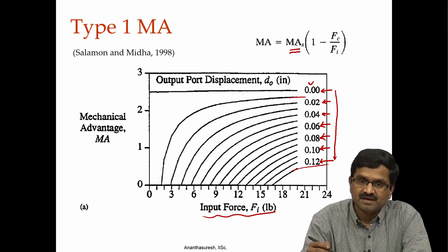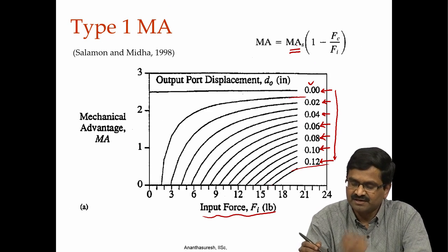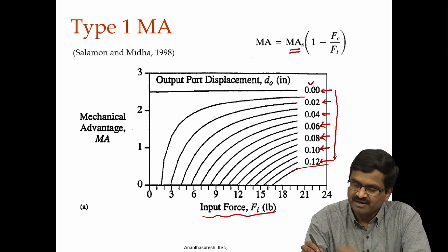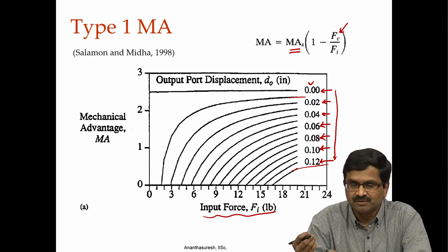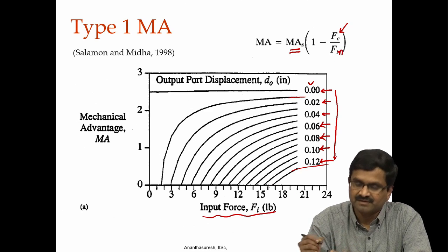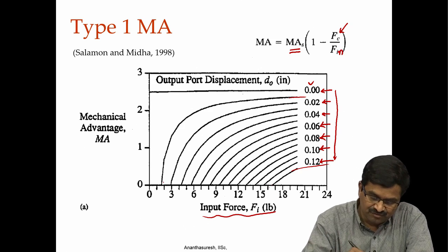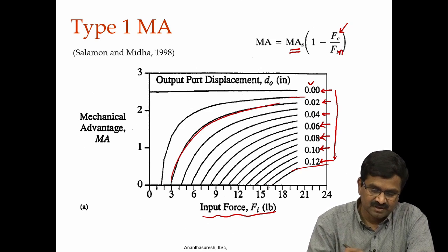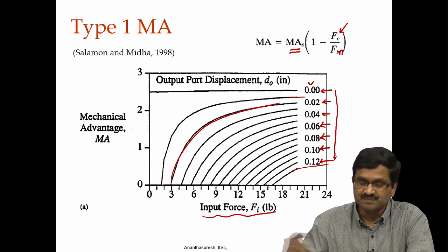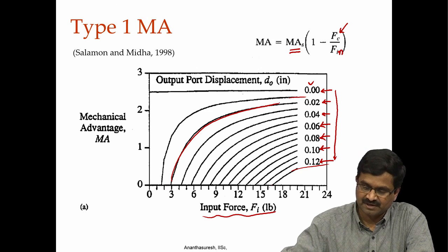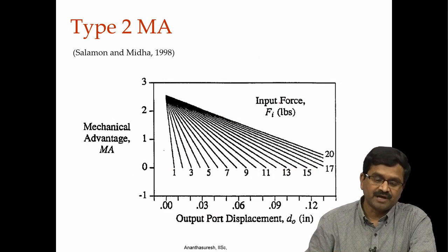They define it as bounding mechanical advantage times 1 minus Fc, that is the force due to the compliance part, that is deforming the mechanism, Fc by Fi in, right. You can actually fit that to this model. They were all numerically done, but you can fit this model because there is inherently this behavior in the compliant mechanism.